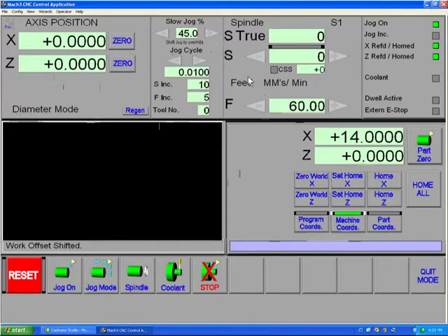Your feed that you've set your machine to is a smart DRO, unlike mill. In this, you select your forward and backward arrows or simply type in a value to be used as a feed rate. This display changes whenever an axis is moving. As you can see, when I jog my Z-axis, I'm now displaying 65.3 millimeters per minute. When I release the button, it goes back to displaying what the requested feed rate is for a G-code move. The increments for the plus and minus buttons are selected here under the F increment button, and the spindle is